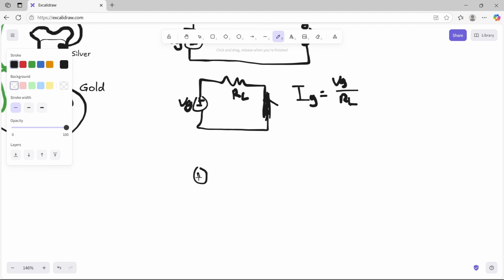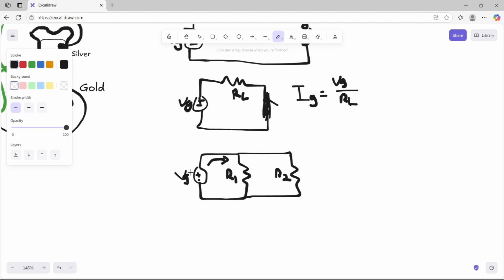Well, let's say that we had two in parallel. This is going to cover Kirchhoff's current law real quick, so we can show you what's going on. So once again, they can be modeled just as simple resistors, nothing too crazy. And I'm not so worried about their actual naming convention, but what we will see, just to foreshadow, is the current coming out of VG will be split between these two branches.